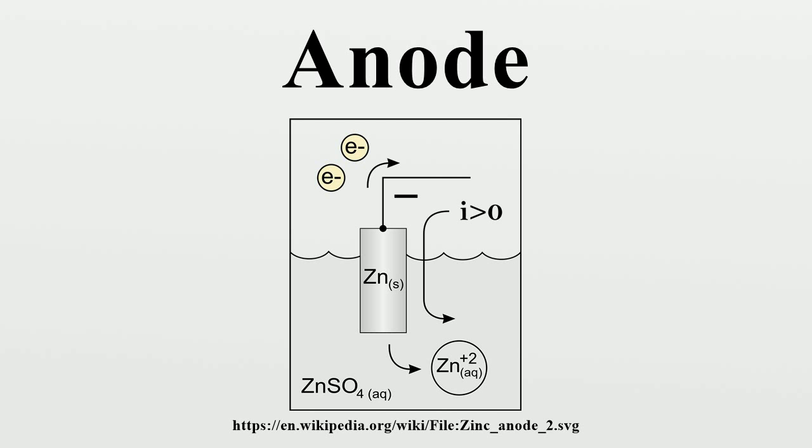Such a coating can protect an iron structure for a few decades, but once the protecting coating is consumed, the iron rapidly corrodes. If, conversely, tin is used to coat steel, when a breach of the coating occurs it actually accelerates oxidation of the iron.